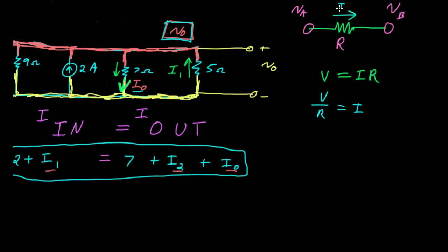So now, if I label that current I right here, how could I relate this current through that resistor to this voltage A, this voltage B, and this resistance R? Really what makes the most difference across a resistor is the voltage difference. I don't care if this is 1,000,000 volts and 1,000,005 volts. It's the same exact thing as if this were 0 volts and this were 5 volts. In the abstract, it's the same thing.